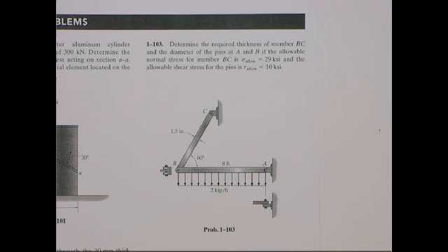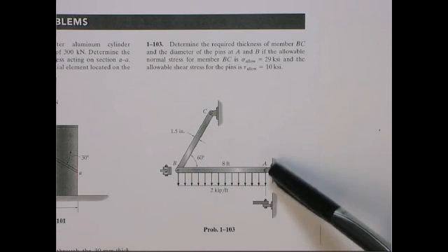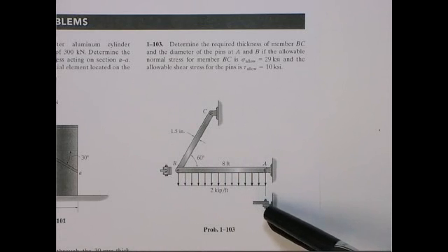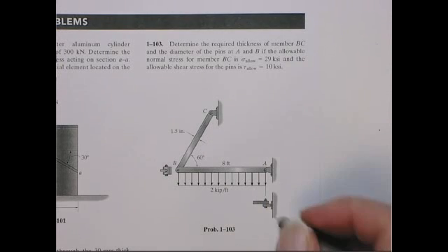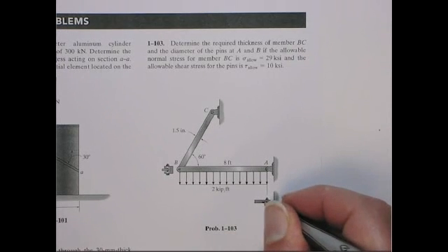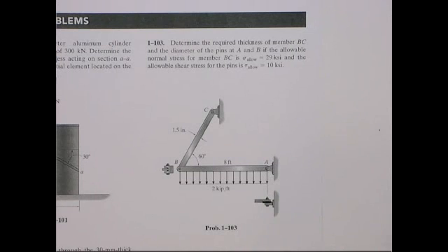So here we have 2 bars, BA and BC. All right. They're pinned together. They're pinned at joints A, B, and C. Those are all pin joints. And you can see here is sort of the top view if you looked down at A. So this bolt going through A acts in single shear along that plane. All right?